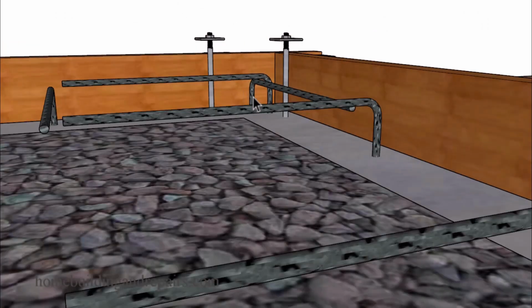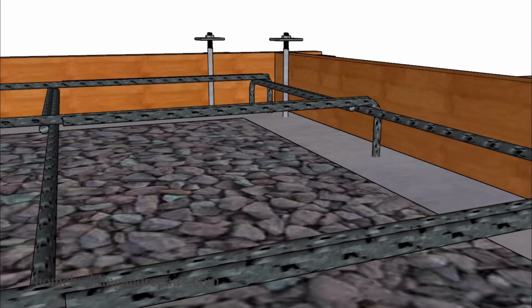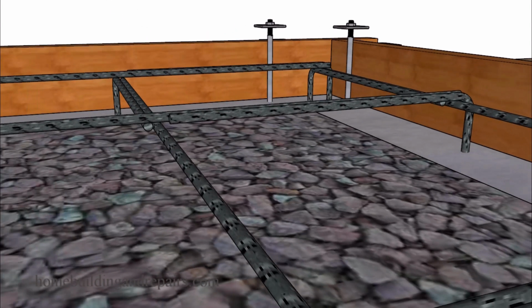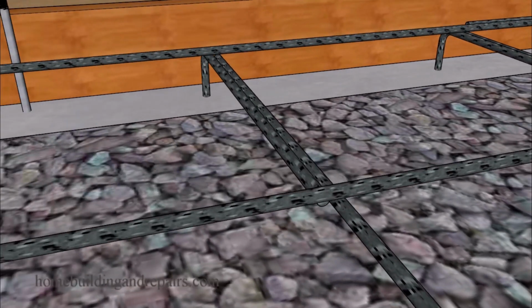And another example of how we have one piece of rebar lower. So the rebar going along this side here is a little lower, this one and this one. And the rebars going in this direction here are a little higher. And again, that's so that our grid will work out. You can see it right here. And I'm not expecting you to make this mistake here because I just told you about it. So the rebar running in this direction here goes under the rebar that's running in this direction here.